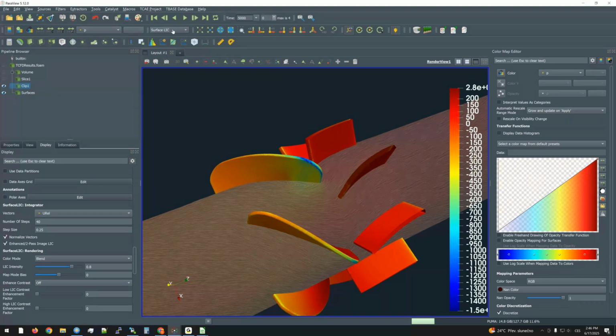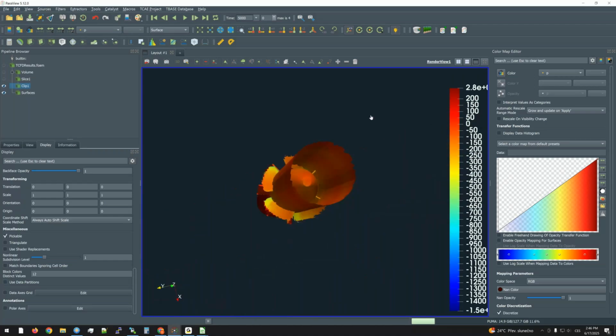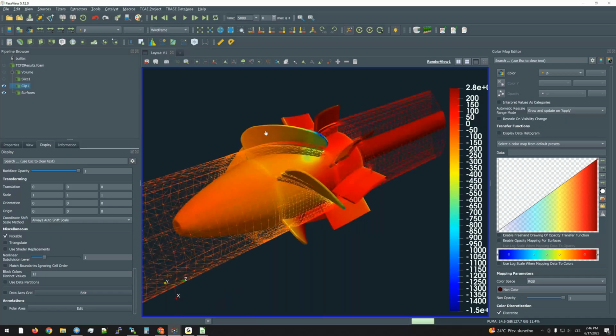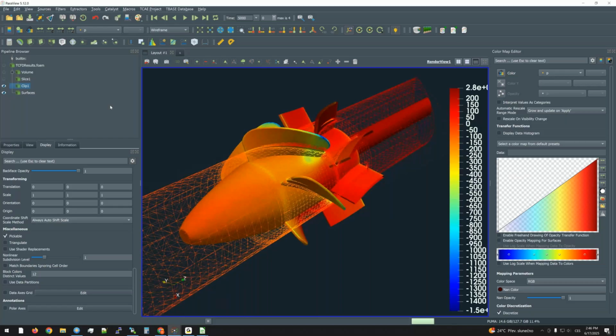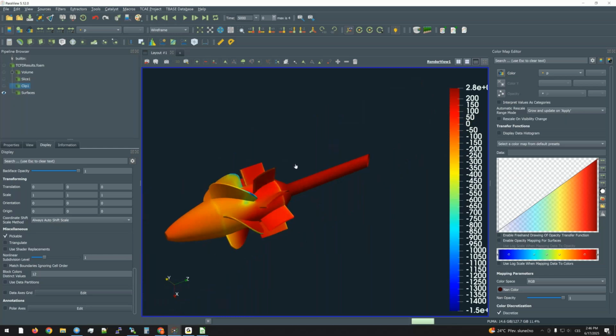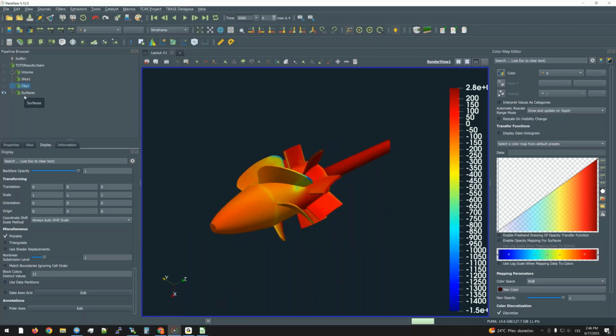So let me uncheck the surface LIC filter and go for simple surface visualization. And maybe then let's go for additional filters to show you. All right, so this was the clipping. You can see you can combine with every, for example, wireframe, and really you can combine with other filters. So let's go for it. So for example, what we can do is to create what I like, maybe if I see the nice surface, is to create a pressure contours. For example, it's a nice visualization.